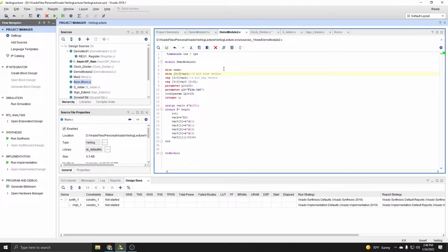For example, in this case, if you wanted to represent a 4-bit variable, something from 0 to 15, you would need that upper number to be a 3. Basically, that's 4 minus 1. I'll show that off in one of the other modules using parameters. But for now, just know that your upper limit needs to be 1 less than the actual size that you're trying to represent.